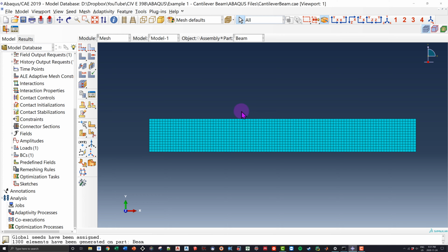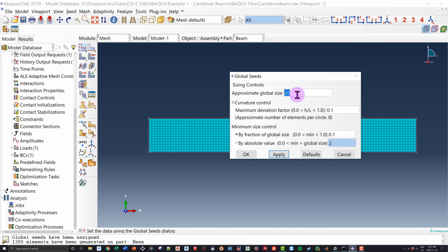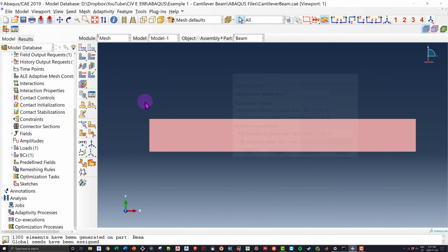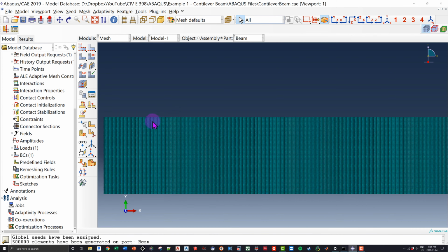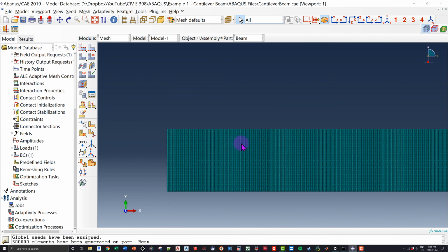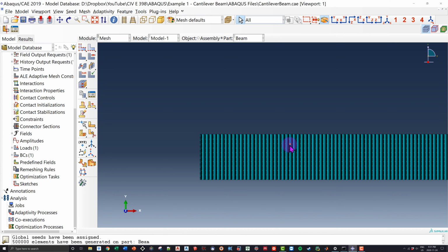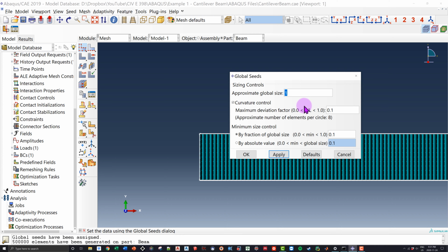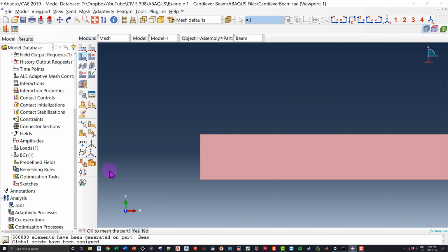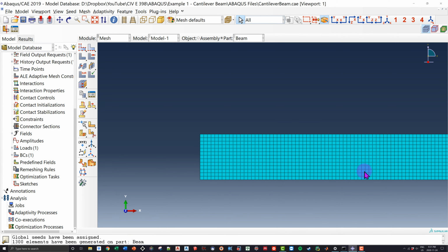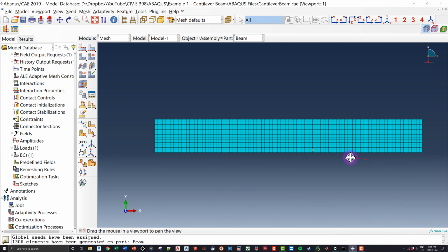As you guys will see, if I want to use a very, very tiny mesh, let's say I go into here, I define my mesh size as 1, I go okay, and then I mesh that part. As we can see, there are so many little squares. Now, the problem with each one of these squares is each one of those squares is a calculation. So the more squares I have, or the more elements I have, the more calculations I have to do. It's going to take your computer forever to do it. So this is where we have to find the nice balance. So I'm going to go back to 20. That didn't look too bad. It looks actually a little bit dense, but this one will capture the behavior reasonably well.